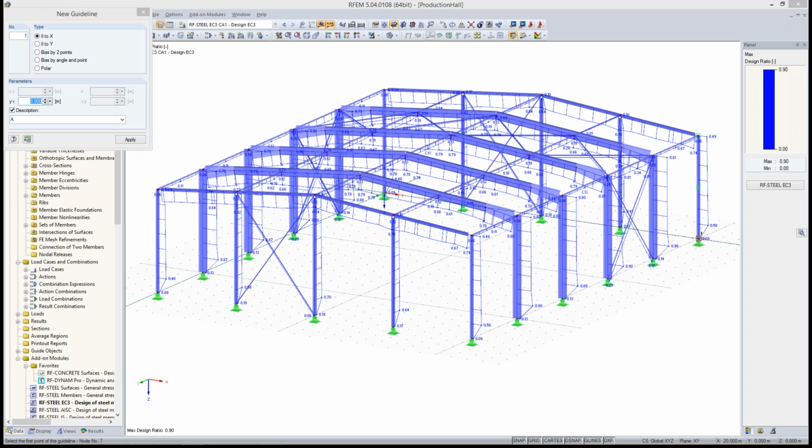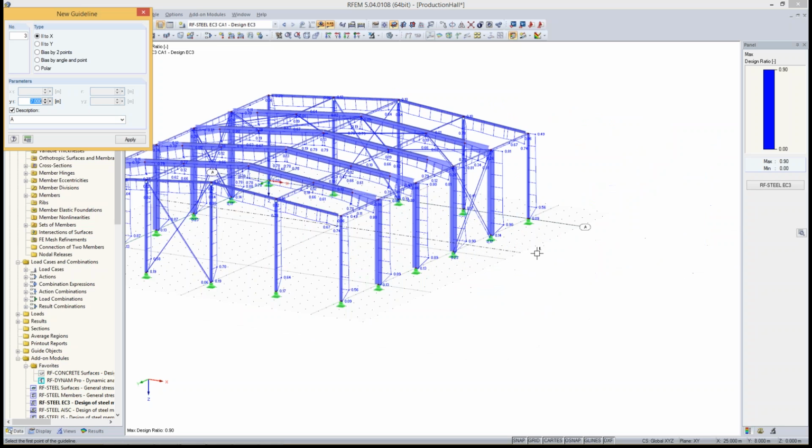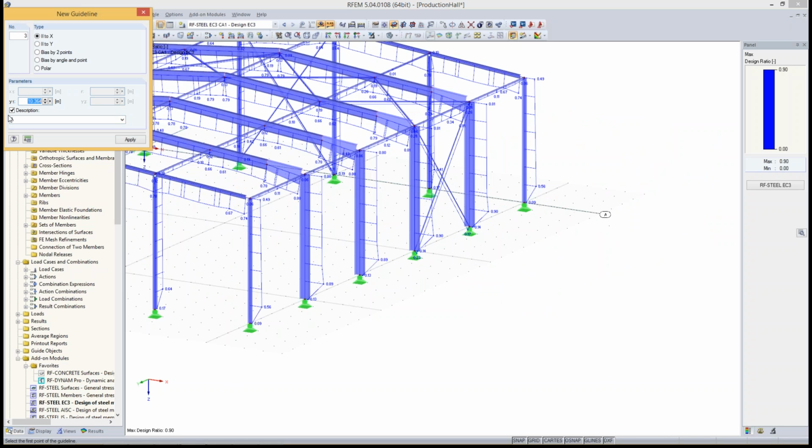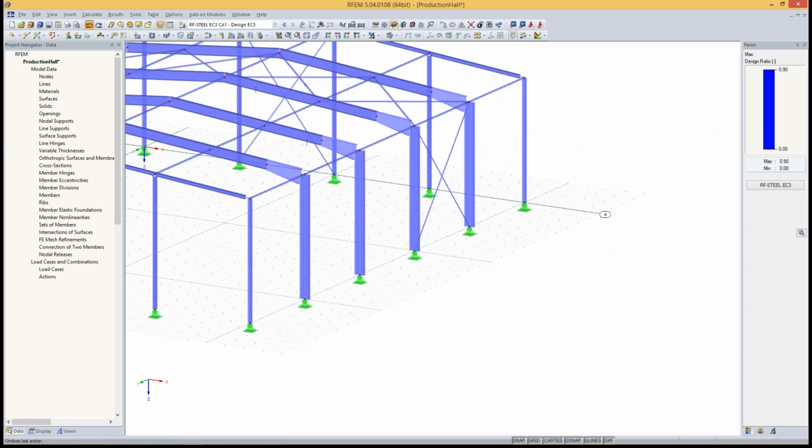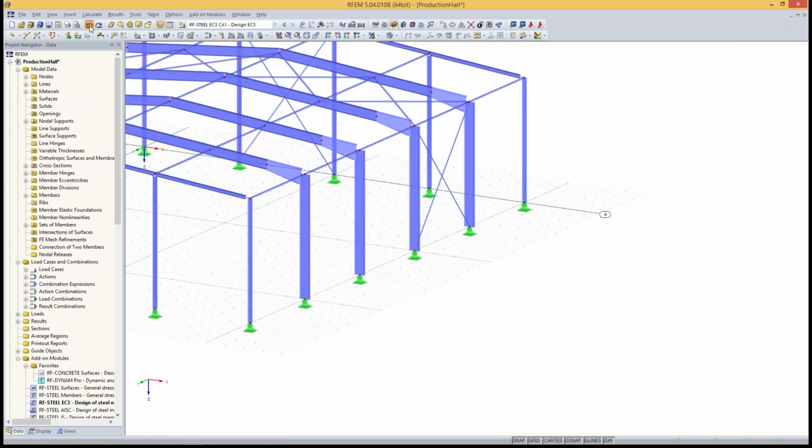And then I click onto this axis and hold on. Here you see that's appearing now, the axis A, and I could do another one and click on this and the B is appearing. And you can do the same parallel to Y and call it 1, 2, 3 and so on. So I don't want to use this, so I go a step back and another one. What I want to use is insert grid lines, align grid.